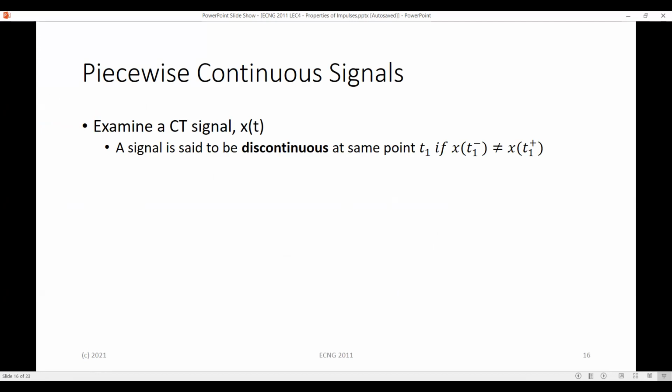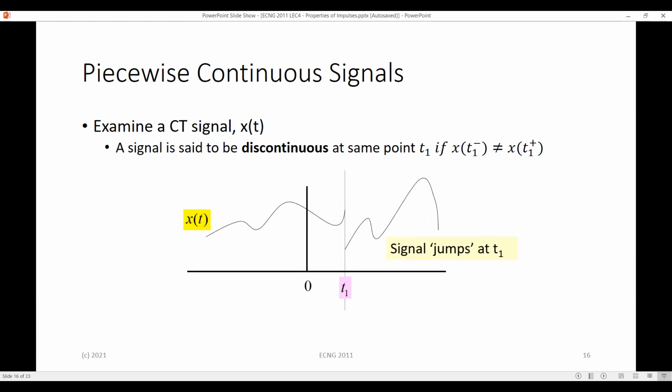The example I had drawn on was a process plant, where a measurement is taking place to control something quite away from a control room, and the information has to be transmitted in some form or fashion. Somewhere along the way, the signal gets lost or broken for a little while. That creates what we call a discontinuous signal, which in plain English means the signal jumps from one value to the other and then continues along the way. That by itself may not be an issue, but